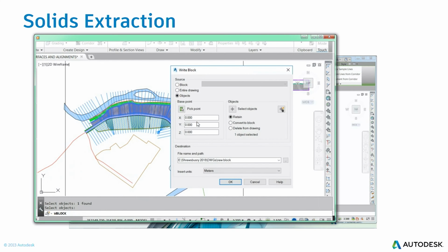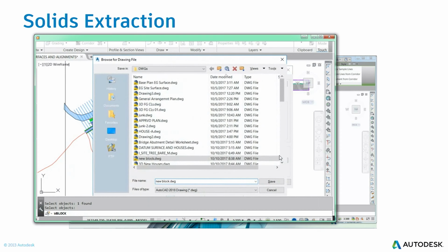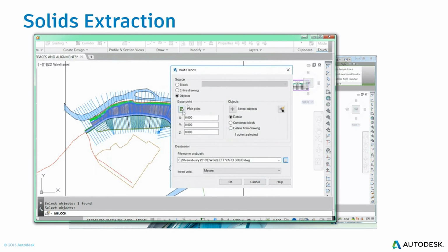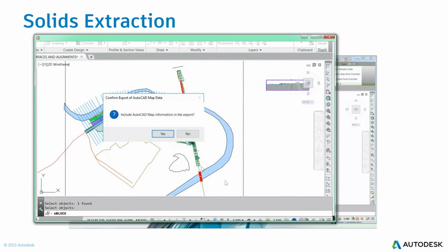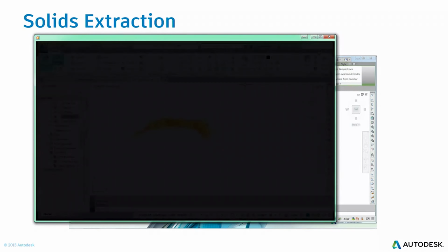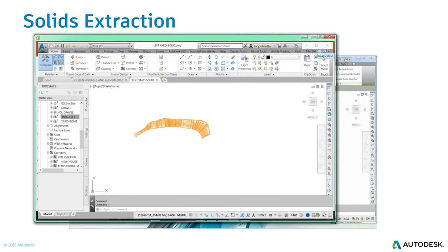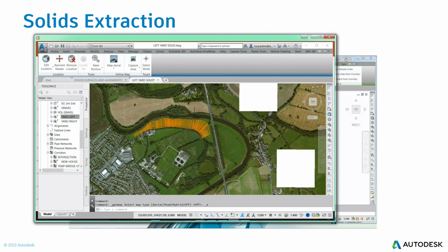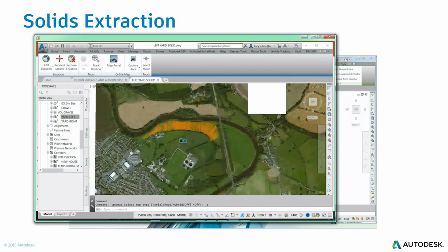Anything that you want to bring into Revit, I'm doing a write block. I'm taking this out at its coordinates, where it lands in the real world. So I'm separating this piece out, but it's still in the real world. And then that write block, I'm going to simply open it up, and that square solid that is the origin of the Revit survey point, I'm just going to insert that. So now I have our piece in the real world, and it's connected to the Revit survey point by this little tiny square, and it has to be a solid, and it has to be in 3D.